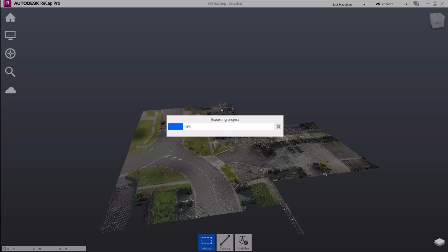The other option that you saw in that home ribbon was the ability to import. If you have other files you're wishing to attach after the initial import, you can just select that option, the one right below export, and you are able to bring in additional files as needed. This includes additional folders. So if you've gone out day one, done a large amount of your scan, imported it to make sure everything's good, realize that something's missing or you need to go back, do the survey again, it gets exported from your scanner as a folder. You can import both that folder and the individual files depending on what you need.